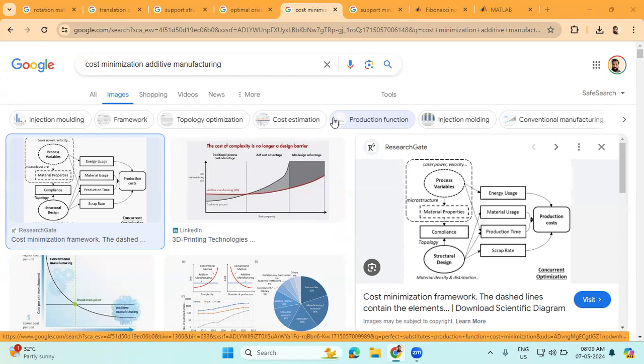Once again, add four times such as model position time, support generation time, model slicing time, and toolpath generation time, and then multiply this time with the staff cost per hour and computing facility cost per hour. Again, you have to add this with the setup cost multiplied with the staff cost per hour plus machine utilization rate.